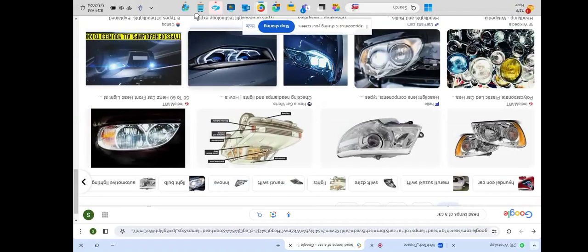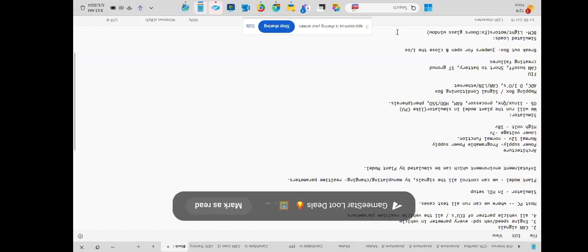So for simulated loads, what I have said is it can be lights or motors, anything. I give the simulated input through the simulator to each ECU, and then whatever output we get, we check whether it is on or not. If I give the high beam on, in simulated loads I can check whether that high beam is on or not. Understood? Okay, that is a simulated load.